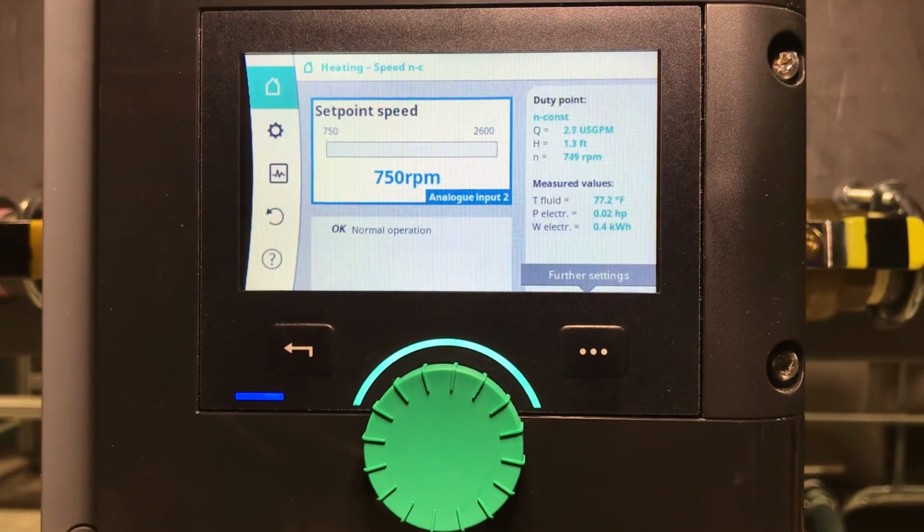At 5 milliamps, the pump should turn off. Perfect. So if my signal goes down below 4 milliamps, it should read this as a cable break. Voila. So the pump now went into its emergency speed mode of 1000 RPM. That's what I told it to do. So if you lose the signal, go to 1000 RPMs. So the pump is set for a 4 to 20 milliamp signal.